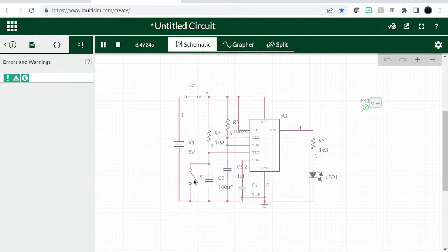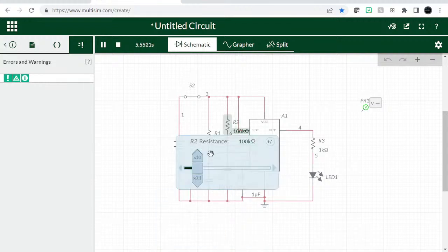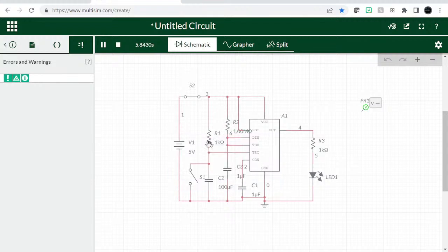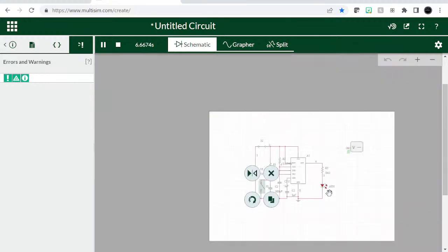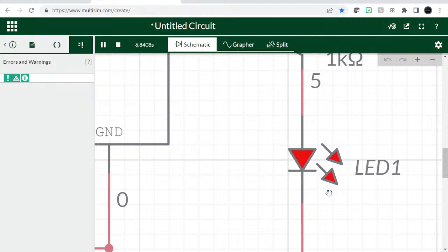Yeah, so when I close it and I open it, it stays on for the monostable period and then it goes off. I'm going to increase the value again so that we can see clearly. No, let's just keep it 100 and then increase the resistor. We can increase the resistor value by a factor of 10, so 1M. When I close this switch and open it again, it stays on for that period and then it will go off. Okay, it's really hard to zoom this, but after the time period, now it's off.